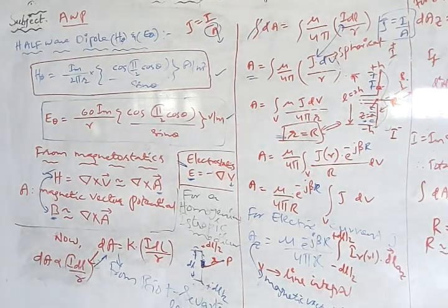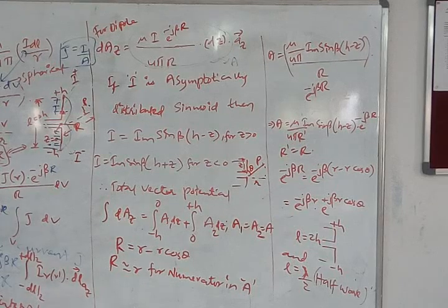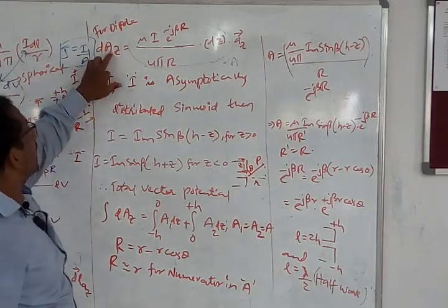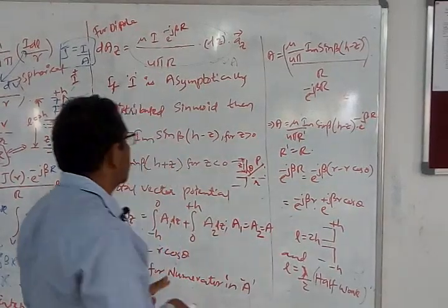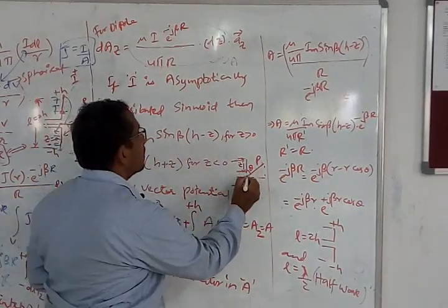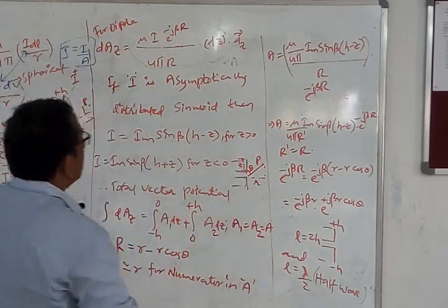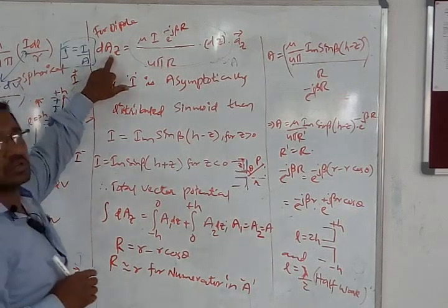Now after we do this, we should extend this to a dipole. Okay, now how do we extend this to a dipole? Now we will write it for the dipole antenna. When you consider it for a dipole antenna, this component I can write as a differential component, because you are going to have two sides of a dipole antenna. A dipole antenna is going to have two things: this is one polarity, another polarity, another pole. Two poles you are going to have. So therefore, we consider that as a differential component, whatever we have got as the magnetic vector potential.